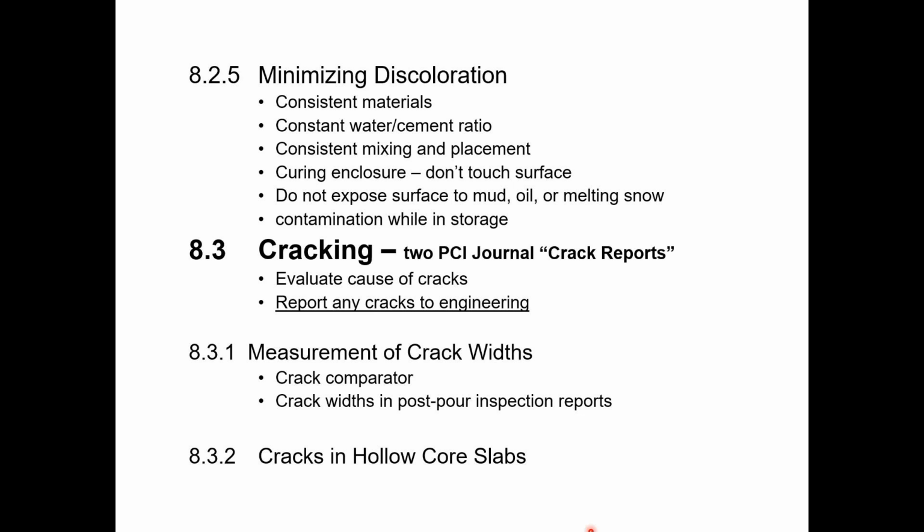But you want to use those resources to help you evaluate whether or not a crack represents a problem or not. It's kind of an industry standard saying that concrete cracks. If you see concrete, it's got cracks in it. It's just a matter of what caused the cracks, and do those cracks now represent a deterioration of the load carrying capacity of that member, or will they continue to allow that component to be deteriorated over time, such that at a future date maybe its structural capacity will be compromised.